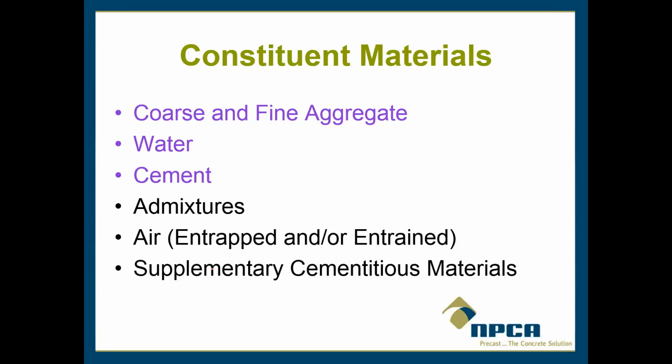So as far as perfect water-to-cement ratio, if you're referring to the ratio at which there is no cement, nor any water left over, I think it's closer to the 0.2 something, 0.26. But the perfect water-cement ratio would not be that in terms of workability. It'd be impossible to cast it and get it around stuff. So I guess the answer to the perfect water-cement ratio is just enough water to hydrate the cement and just enough water to achieve the workability you need to get full envelopment of the reinforcing aggregate, so whatever that may be.